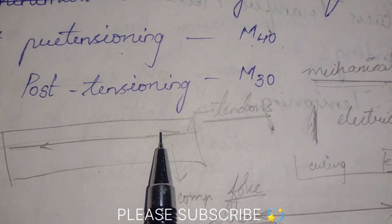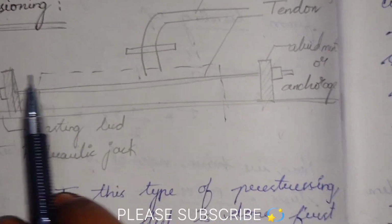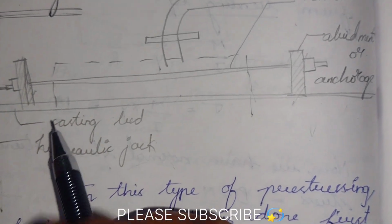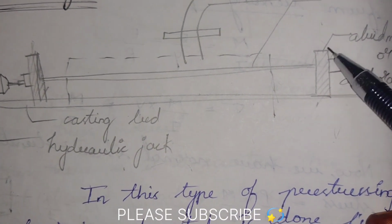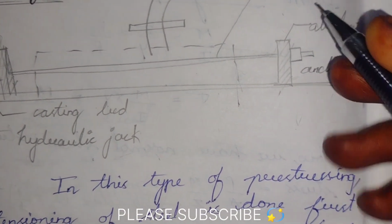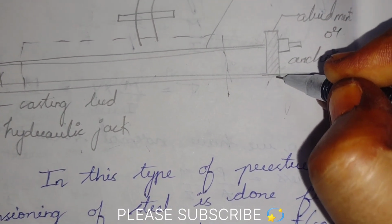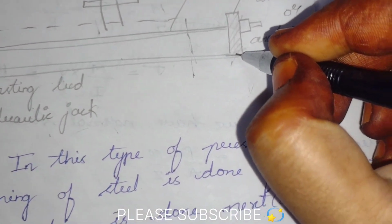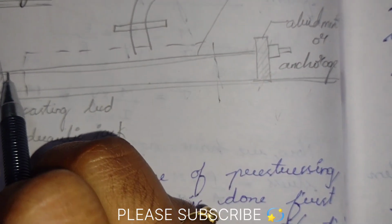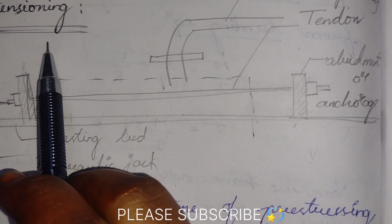Let us now see the systems of prestressing. This is the pre-tensioning system. As the name explains, in pre-tensioning the tendons are first tensioned between some rigid blocks. These are the rigid blocks I am talking about. They are cast on the ground or in a column mold. This may be a unit mold that is separately cast, or it can be directly cast on the ground itself. This bottom one is the pre-tensioning bed. These are the components of the pre-tensioning system. Understand it very clearly.